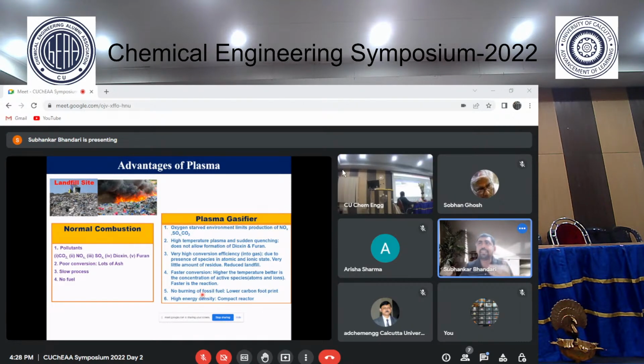It is well above the disintegration temperature of dioxin and furan. Above 800 degrees Celsius, dioxin and furan just disintegrate, and at the downstream we suddenly cool the off gases. Dioxin and furan basically form between 200 to 600 degrees Celsius. We have designed our system in such a way that we don't experience this temperature range, so in our system, dioxin and furan are not allowed to form.